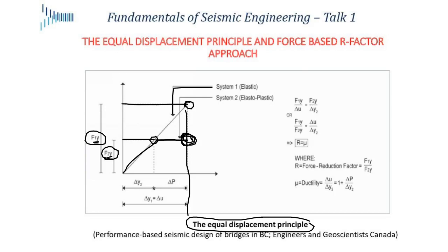The trick is that I have to be able to travel, or my structure has to be able to traverse this path. I'm going to call this the elastoplastic path. This is a bit of a generalization. Real structures usually are not fully elastoplastic, but to illustrate the point, this is where we're starting.